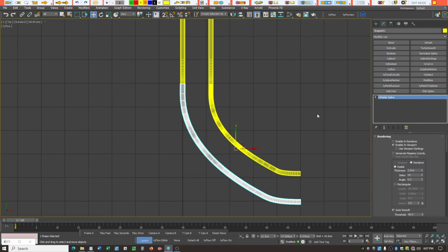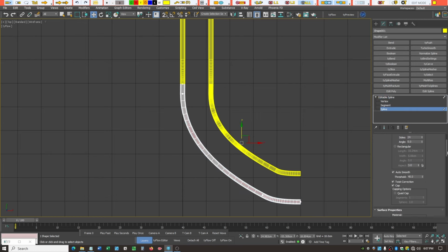So now we need to create an offset again, right? So if we go in here and select the spline like we did before, now we can come down here and find the outline again, and this time we want it to go to the outside. And I know from playing around that we want an outline of -3, right?